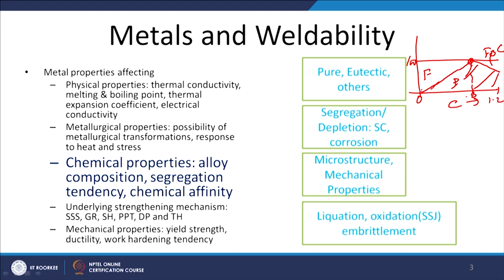So, the pearlite fraction will start decreasing and the iron carbide or cementite fraction will start increasing beyond 0.8% carbon. And if we see its effect on the mechanical properties, there will be a continuous increase of hardness with the increase of carbon content, and the strength will increase up to the eutectoid point, and thereafter strength will start decreasing, while the ductility and toughness both will be decreasing with the increase of the carbon content. So, both mechanical properties and the microstructure are affected by the composition.